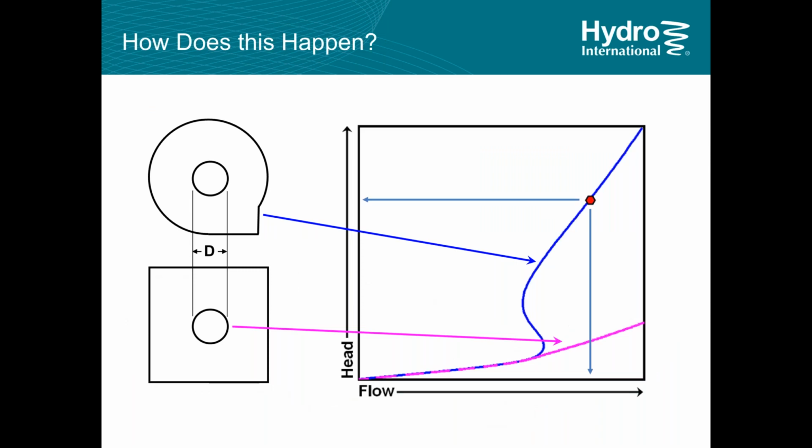And a vortex flow control is a sort of constant discharge valve in a way. If you're somebody who deals with orifice flow controls regularly, you'll recognize this sort of head discharge curve, where if you have an orifice and your flow starts to increase, your head starts to increase as well, usually based on the square of the velocity. So you end up with this sort of curve here.